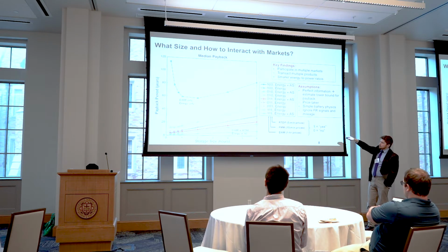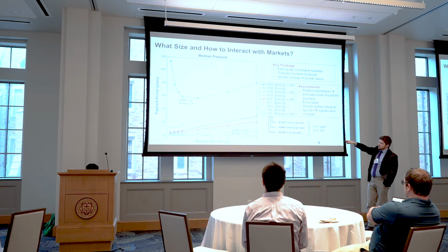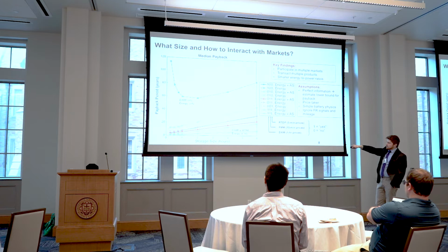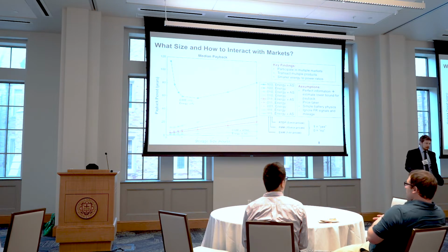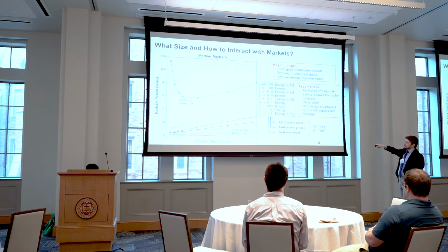So if you were to build one of these batteries and only participate in the day-ahead market, so that's only the hourly, and you're buying and selling energy, your optimal size is about 2 hours, but it's going to take you 60 years to pay it back. So that's not going to work. But if you transact some of these ancillary services or go with the faster time scales, these lines get much better to where the payback period becomes a year or 2. Okay, now that actually makes sense.